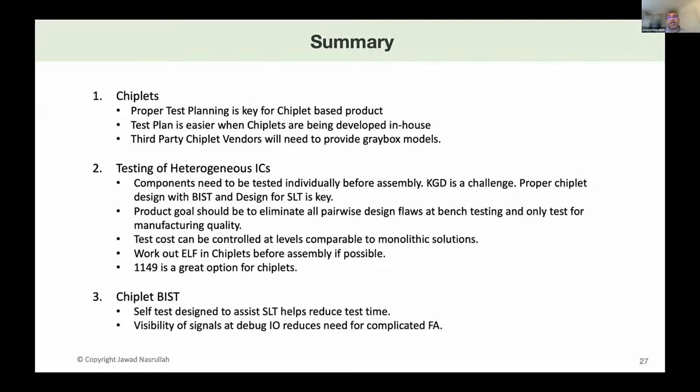Yes. That's where manufacturing is improving daily, but we always keep moving along technically. Like copper pillars were not enough. Now we are doing copper to copper hybrid bonding, and that has its own set of issues. Yeah, I think this speaks to your earlier question about reliability on multiple reflow cycles and things like that as well. Right, causing degradation over time.